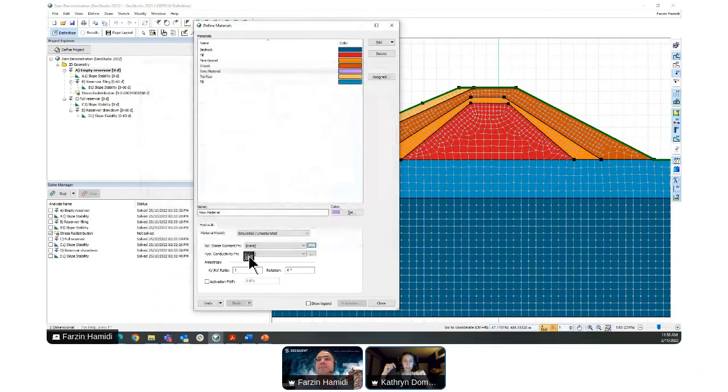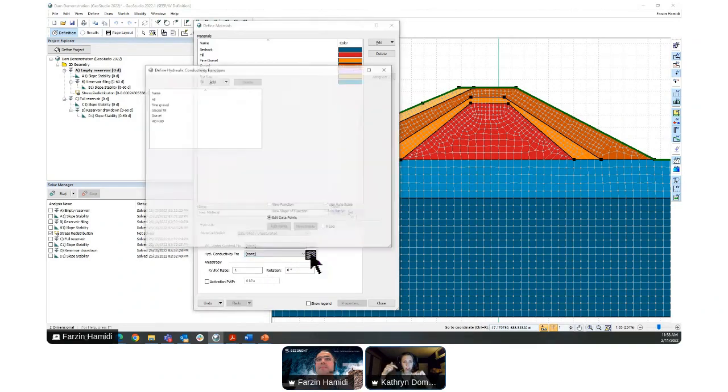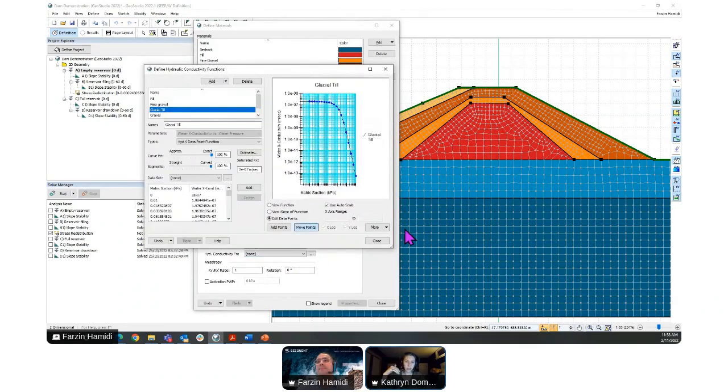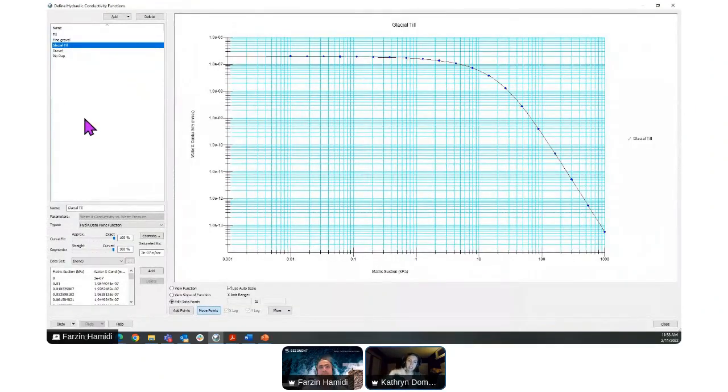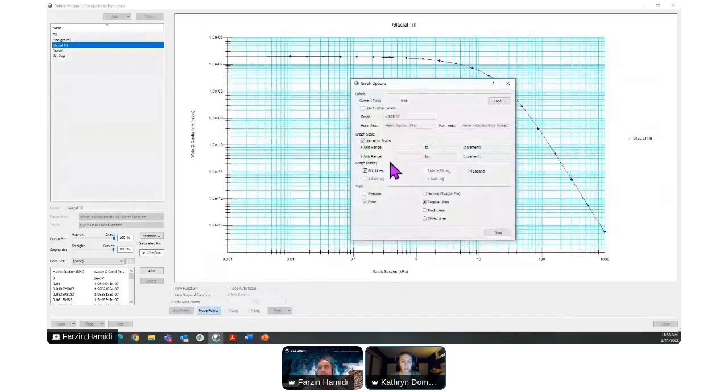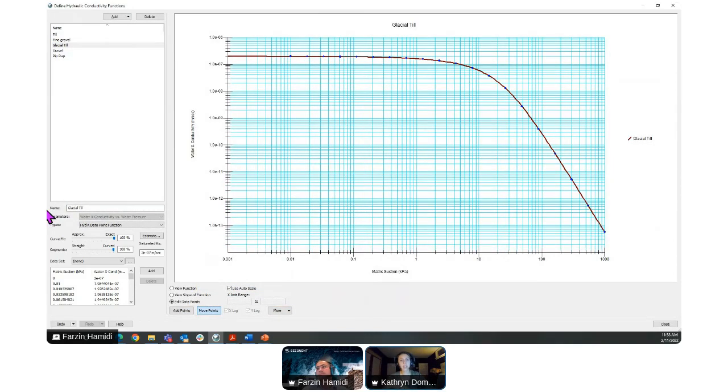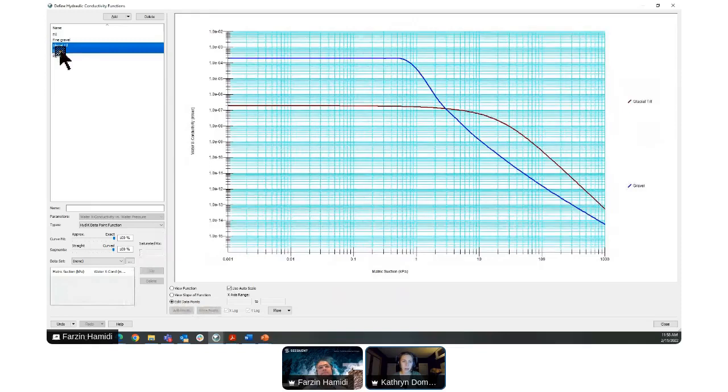So you can just determine the amount of water that's coming in, the average infiltration rate. Assume that that's your hydraulic conductivity value, and then, based on this curve, calculate the corresponding pore water pressure value. And that gives you an approximate value for what your pore water pressure would be at that given hydraulic conductivity, or your infiltration rate, for example.